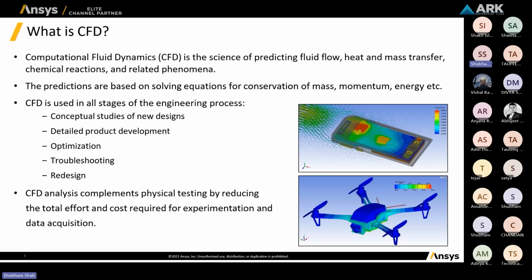So you have to redesign it, you are designing a new product or you are trying to optimize it. In simulation, you have identified a hotspot zone which is near your fan location, and you want to reduce that. There are possibly two ways: you can go with a higher CFM fan for the exhaust fans, or you can make a design change.